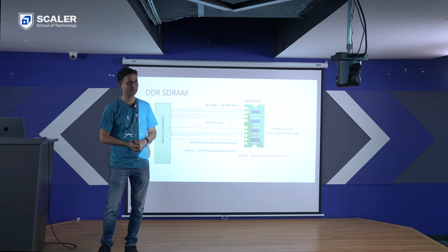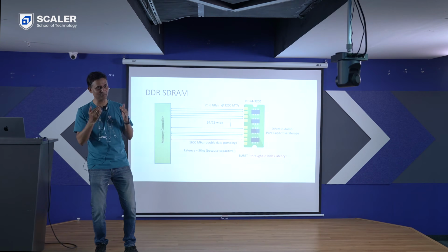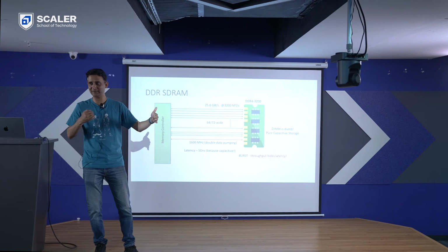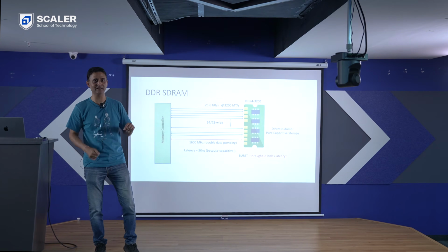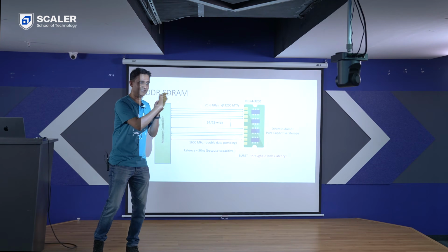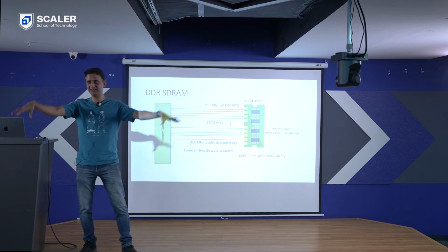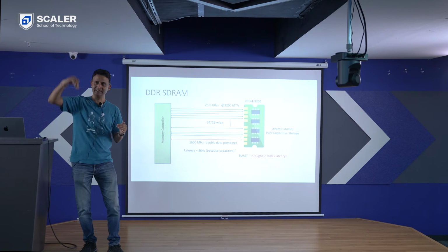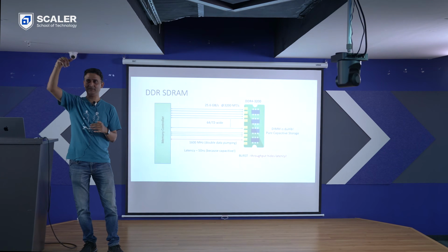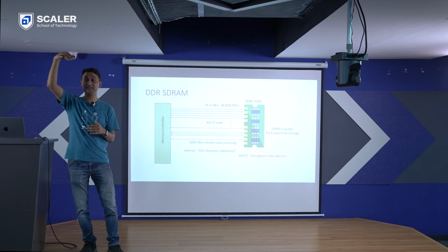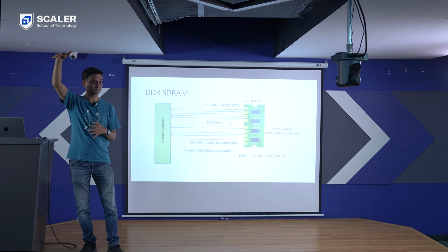This is known as burst. By the time those 32 are being transferred, just at the end of it, I switch on just the adjacent cell. So in memory structure, because of the charging and discharging, a large part of that time is actually known as a pre-charge step.